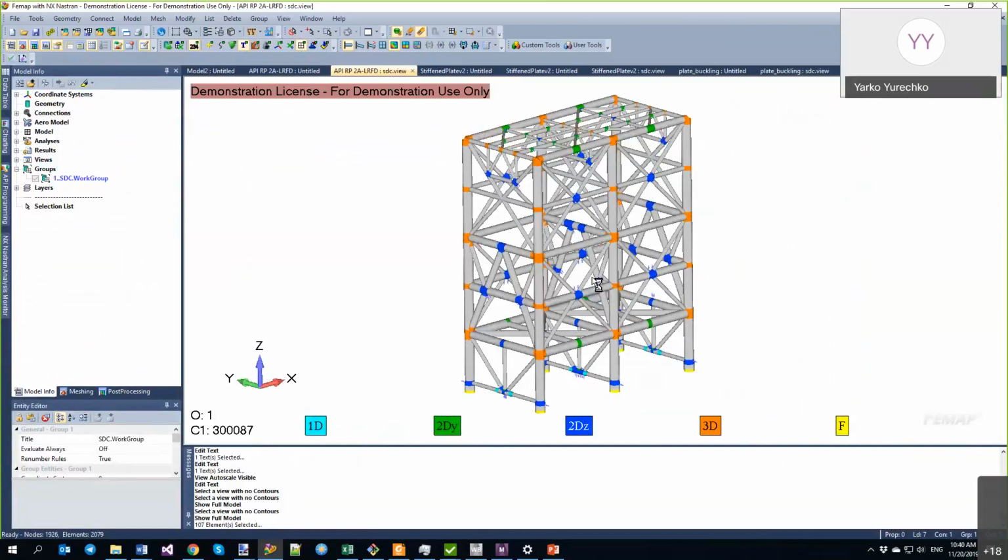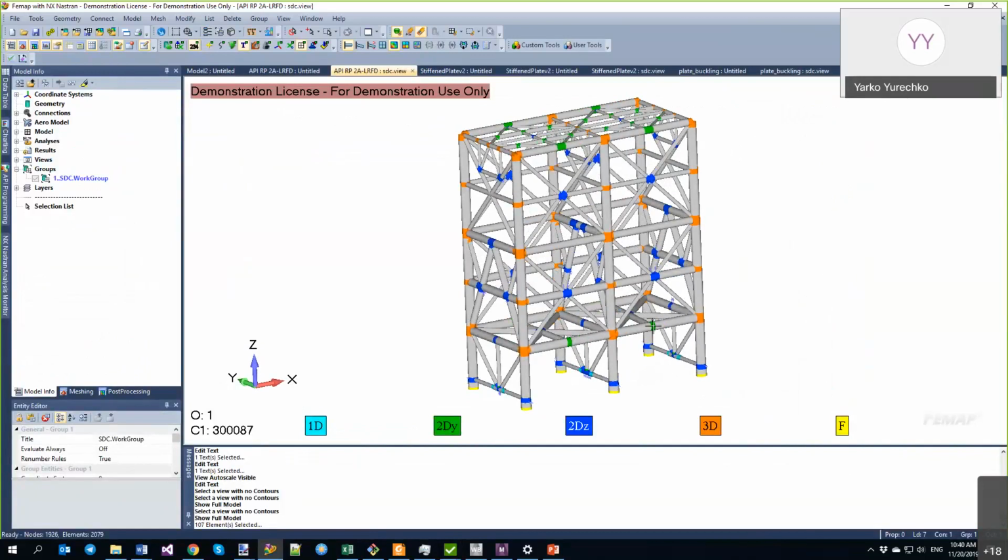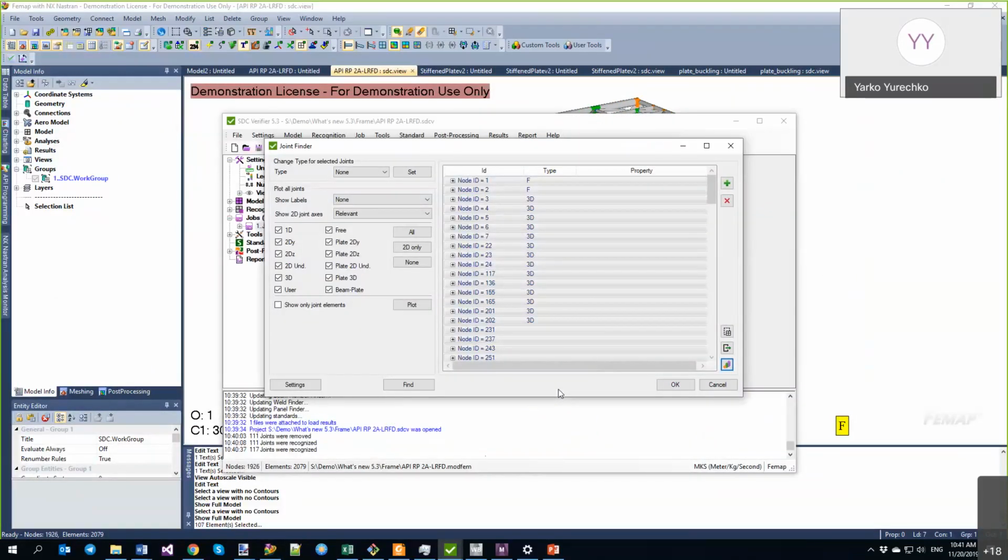As well, if you have a joint added somewhere in the middle of your model, it can be combined with a connected beam. So, for example, if I add a joint here, it will treat that not as a 2D joint but a 3D joint. So it's not treated only from fixed to non-fixed, but it takes into account the type of the joints.